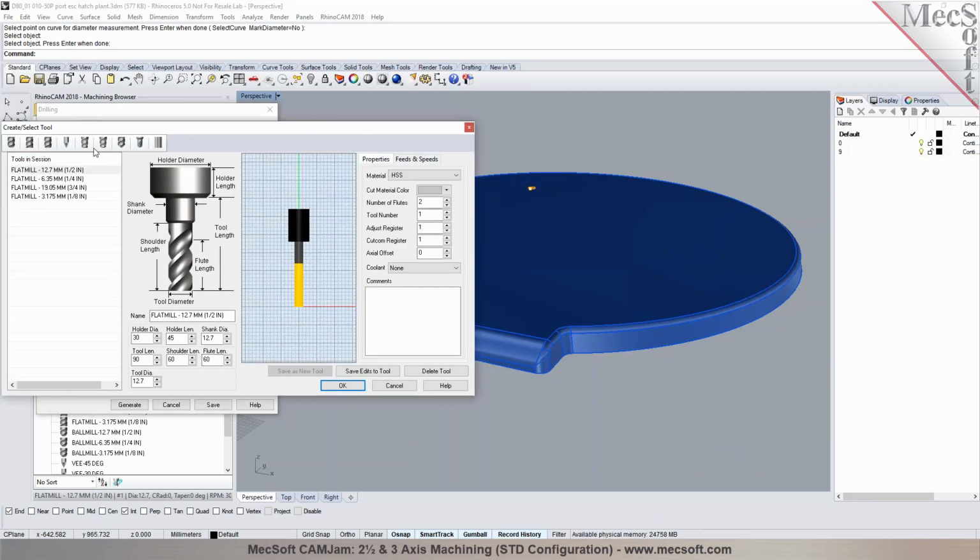And I can define a drill tool in here. And I can go into the tool tab. I can even use an end mill for drilling. Or if you want to use a drill tool, you can specify it. And you said it was a 3/8 end mill? Yeah, exactly. 9.525? Yes, exactly. Okay, so we can put it in there. We can say drill 3/8 or...